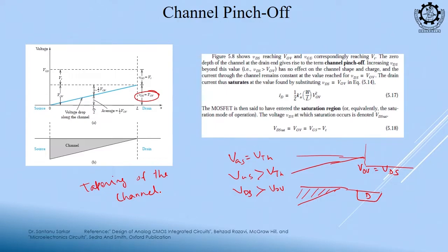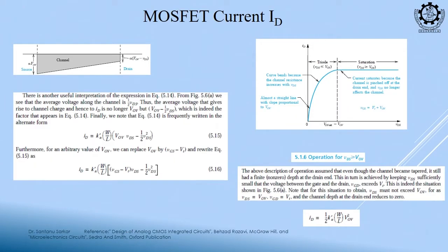How is this tapering happening? With the drain potential. So, this is our ID versus VDS plot. This region, we will know in MOSFET, is known as the triode region or linear region. This terminology is different from the BJT. In BJT we call this region the saturation region. In MOSFET the terminology is just different, do not get confused,